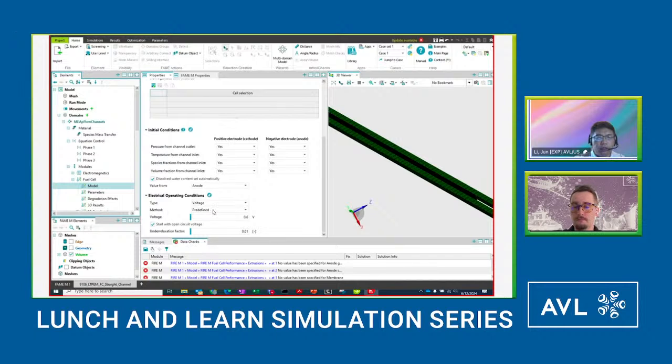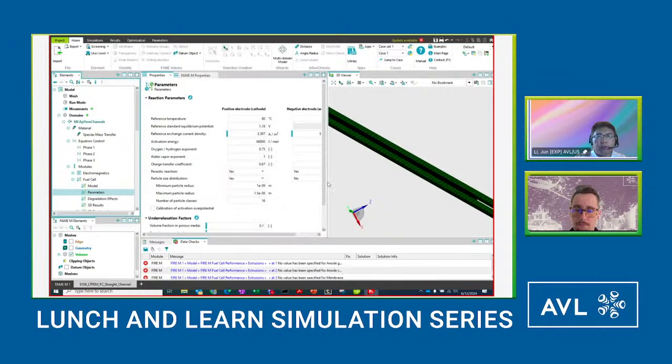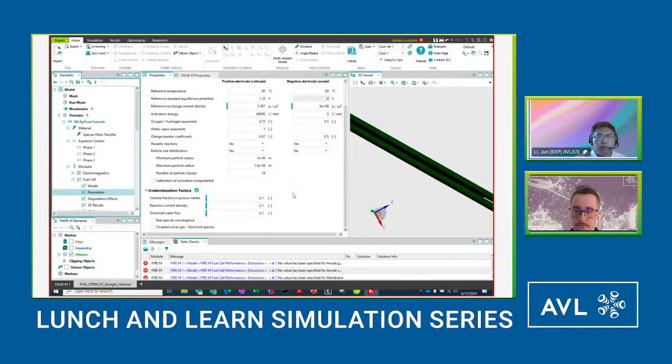You can use a predefined voltage of 0.6 volt, or you can use the operating current density to specify a current density. And then if we activate this one, the simulation will start with the open circuit voltage and then go down to 0.6 volts. So this way, the simulation is always stable. And then we have some parameters for the fuel cell that the user can specify.